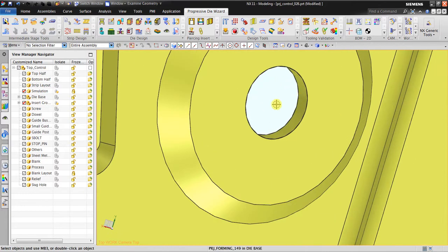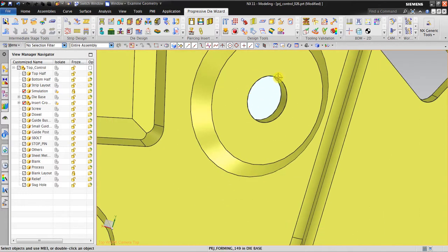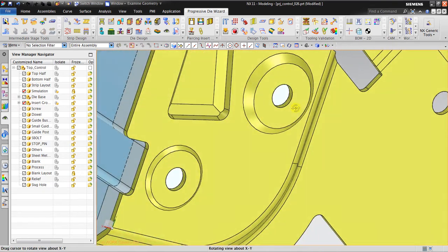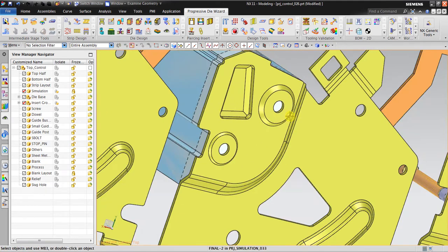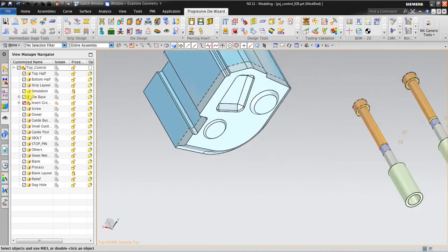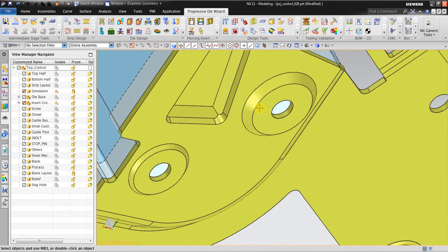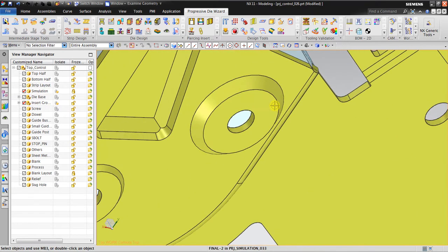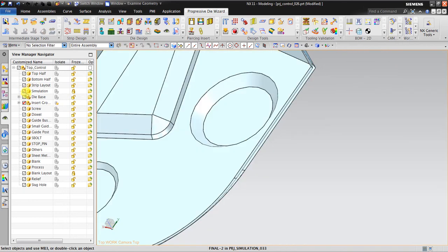As you can see here, we have a hole, but I click the upper face, so it means that it will just create a straight surface. It will close the hole here, like this one. So you don't need to worry if you find some kind of hole here. You don't need to close it, just click on the top surface, and it will be closed like this one.